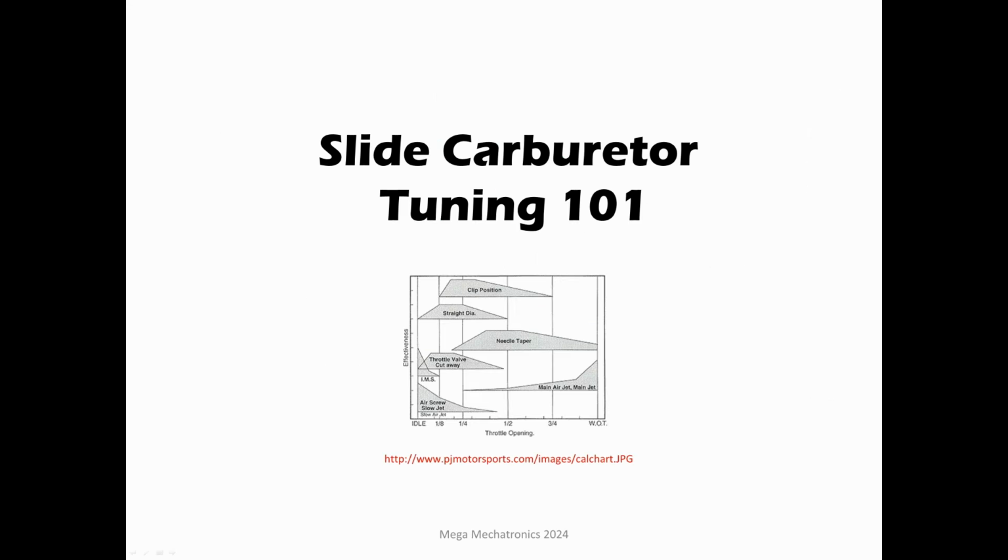So you want to go out there and do it. Either grind away so that you can get to that whisperer level, which is going to take a lot of work. Or you can save a bunch of time and save a lot of frustration by going to a wideband oxygen sensor and even an EGT. But that wideband, that's the key. That is the cheat code to figure this out, where you need to make those changes.